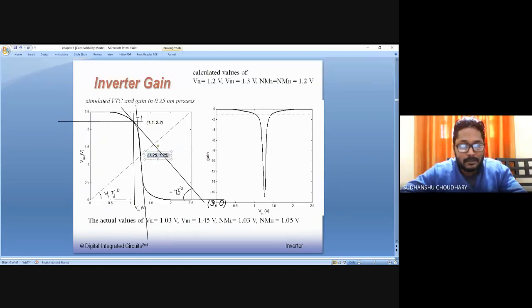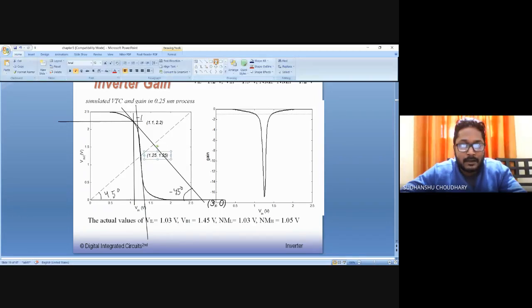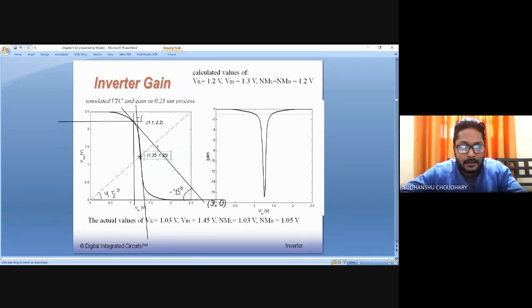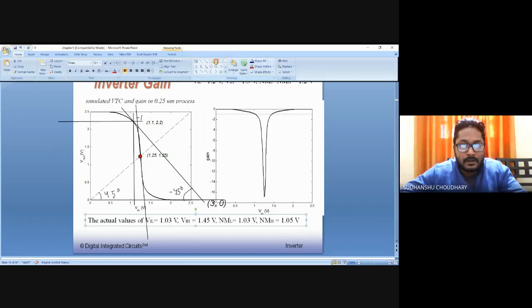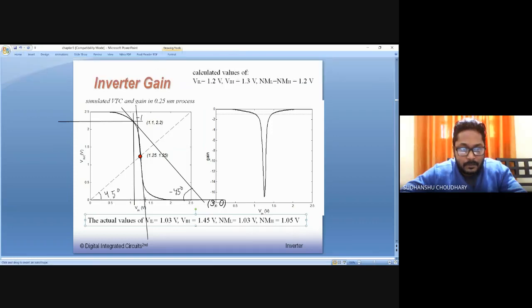Let me make it a little bit small. Right. So at this switching threshold VM, the coordinates are, I mean, we considered about this point now, and we are also concerned about this point where this tangent is touching. So the coordinates of these 2 points, this is 1.25 and 1.25, and this one, y is 0, but x is maybe, let's say it's somewhere around 1.3, right?